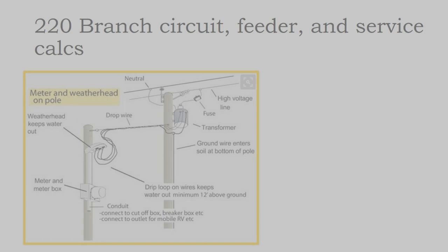All right, let's study this picture. This is something I definitely was scared of when I got into the solar industry, because often you'll be designing your home and the utility will want you to install the meter box and the masthead and the weatherhead, and even put in conductors all the way up to this point. And then the utility will come along when they establish a new electric service. You have your higher voltage power lines coming in from the utility, and then they pick out a transformer for your electric service. In this case, it's a 240 volt split phase.